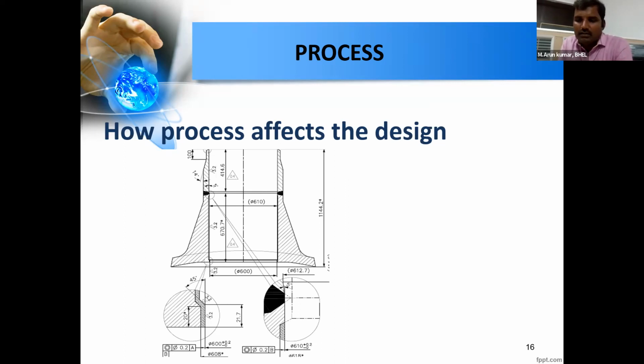Whenever there is a susceptible atmosphere of steam water mixture and some tensile stresses that might have developed during our manufacturing also, austenitic stainless steel material is prone to stress corrosion cracking under a steam water atmosphere. So what we are doing over here, we are making an austenitic stainless steel build-up, and we are welding the material over this.